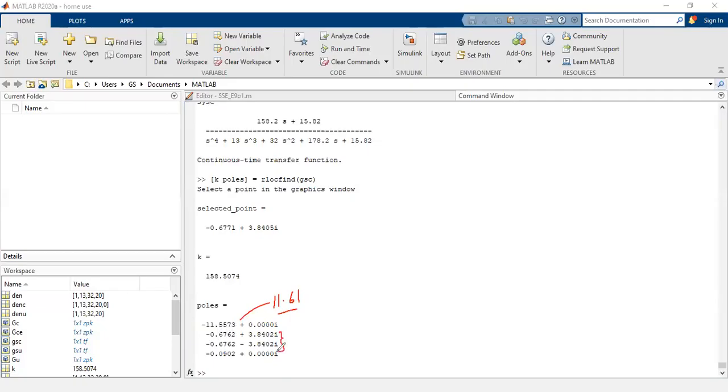These are the 2 second order dominant poles. And the other one is between the introduced pole at the origin and the zero. Those two are very close, pole here and zero here, but their exact location has also been figured out for that particular value of gain K.